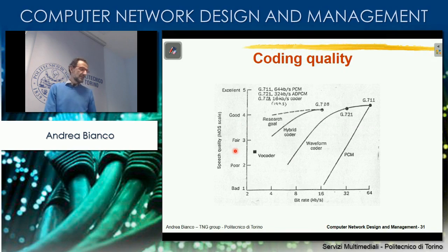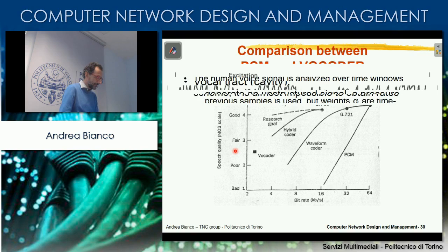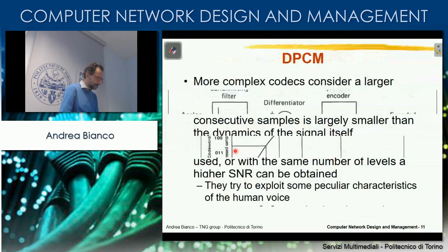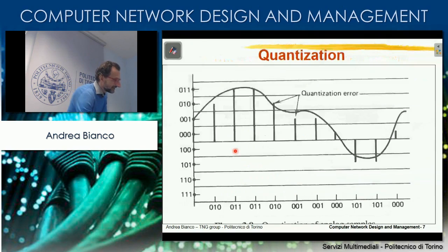Now, in terms of what is important for us, besides having some idea about the coding technique that we use, the basic concept here is that if you look at the original PCM scheme, which is coding this, here it is. Okay, in this case, if you made a mistake in detecting at the receiver this level, this is actually tolerable from the perspective of the human user. Why? Because basically what we do at the receiver is a process in which we smooth out this signal, we filter it, and this filtering operation would of course compensate this error on a given sample. So a single error or a few errors are fairly tolerable in this type of application.